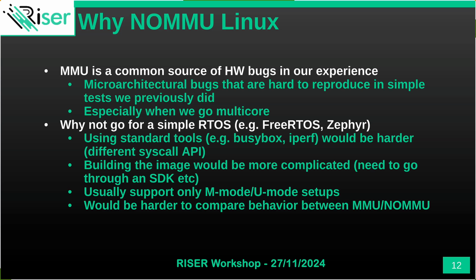Also another thing is that it's easier to maintain. When you want to build an application for an RTOS, you usually have to go through an SDK. If you play with Zephyr or FreeRTOS, it's a different build flow that you have to follow, which is more complicated if you think about it. Because if you just go with Linux, you have the same toolchains, the same tools for building the full-blown distro, and you can use the same tools for building something very small. So if you put in FreeRTOS or Zephyr, or I don't know, Yocto in between, you'll suddenly have a lot of dependencies. You'll suddenly depend on an SDK or other stuff that will complicate the flow of building these images.